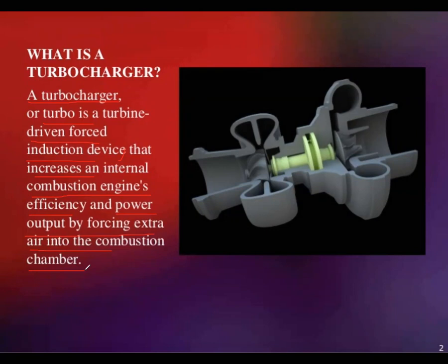because the exhaust gases carry some velocity, some pressure, and some temperature. The velocity, pressure and temperature of those gases strike the turbine blades, so that the turbine blades rotate with that velocity. Whenever the turbine blades rotate, that energy is utilized to run the compressor.